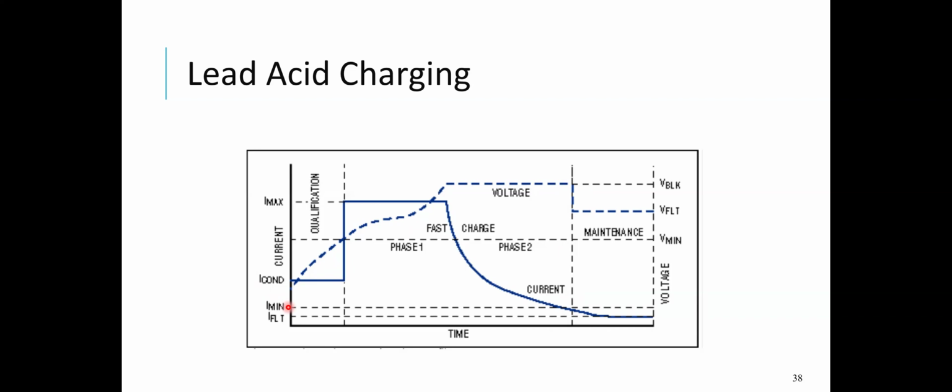In the case of lead-acid batteries, what we do is once we fully charge the battery, we reduce the voltage from a charging voltage to what's known as the floating voltage. And we leave the battery at this floating voltage where the chemical reaction keeps occurring, but the chemical reactions take place so slowly that there's enough time for the produced hydrogen to recombine and make water without the valve of a sealed lead acid battery opening.